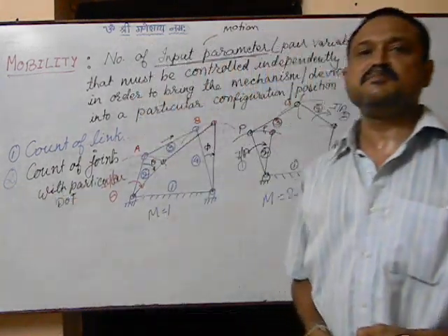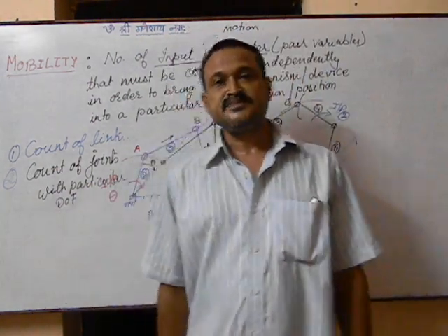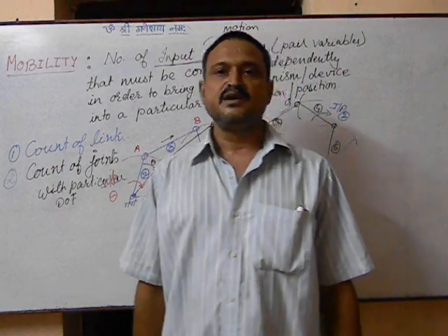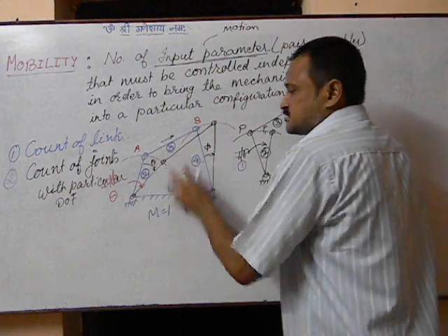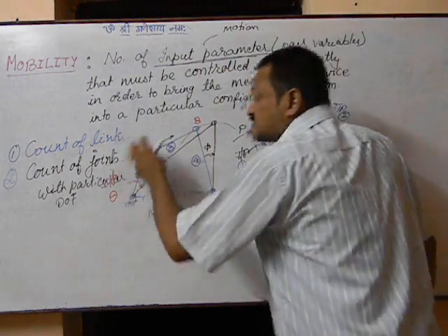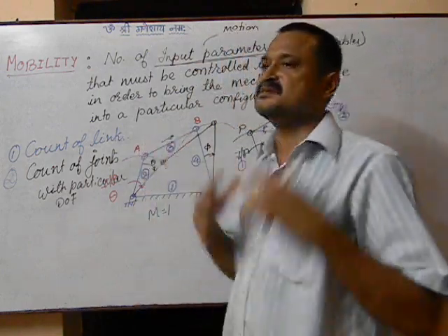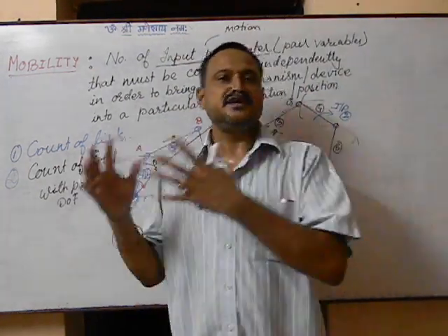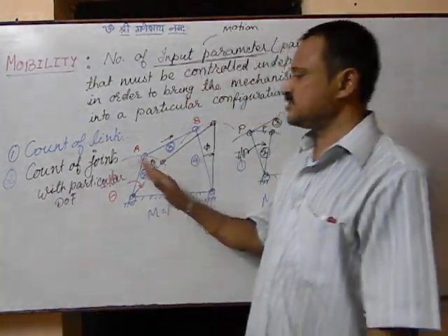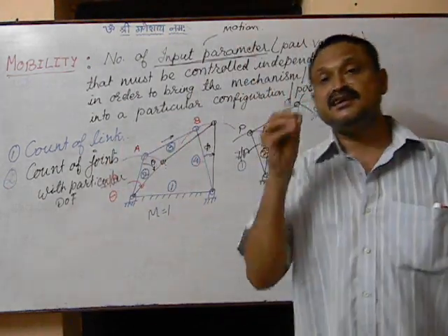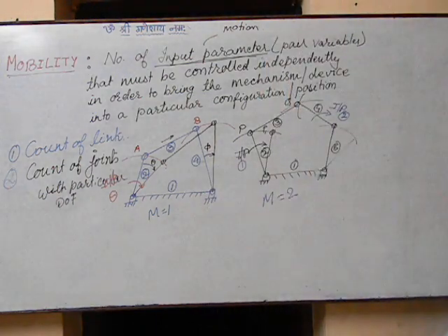See, why this is important is we know every joint is going to impose certain restrictions. So when all the joints are imposing certain constraints, or all the joints have certain degree of freedom, then definitely a mechanism will have a particular degree of freedom, and it will be dependent on the degrees of freedom of each and every joint involved in that mechanism.